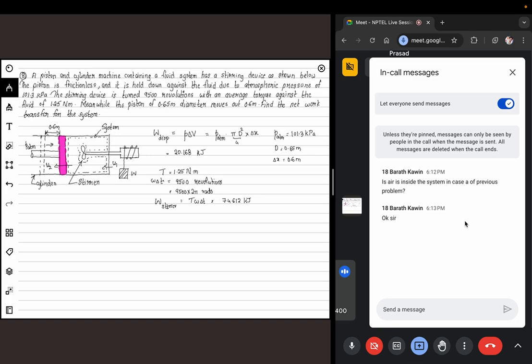So who is doing this work? You are supplying this work to the air indirectly. So this is a negative one. So what is the net interaction? This is the expansion, the positive one, and then you have the work that you are doing on it from the stirrer. So then it will be coming to around minus 53.994.